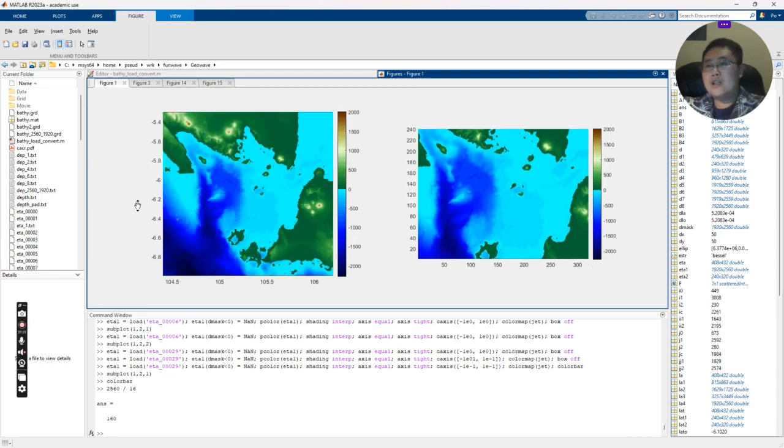I tried to put this particular bathymetry file into funwave, but the problem is that the code is going to blow up, so I'm going to have instability problems, right? So for this particular input, I have too much land. The green areas are all land, but tsunami waves propagate in water.